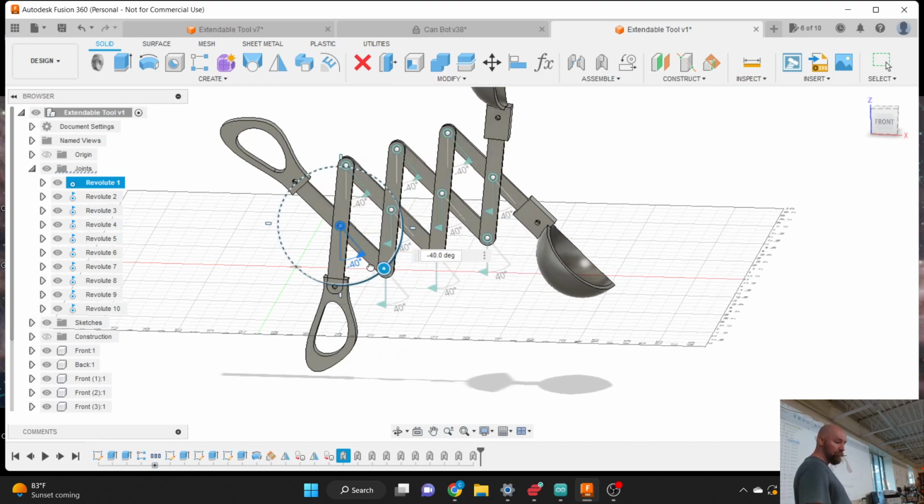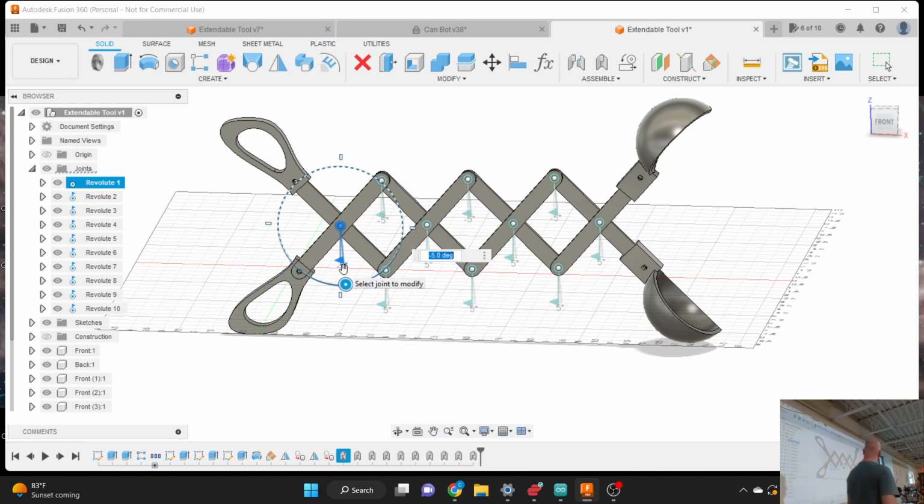Okay, Carl. I have a question here. On this one particular joint, it is not letting me put my hole-in-one flag where I want. All of the others are facing down and left. This one right here, no matter what I do, it will not let me do that. Try looking a little bit more three-dimensionally. Try moving your navigation cube and kind of look. Sometimes if you choose the edge of the circle, there we go. Okay.